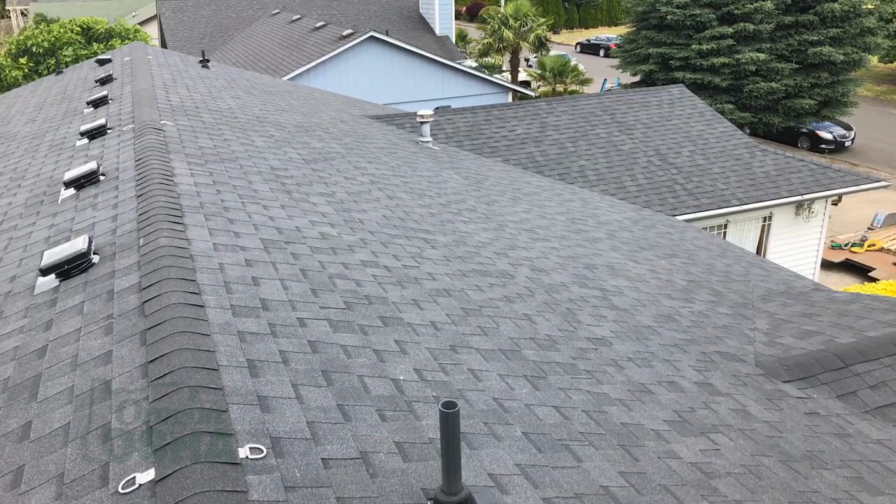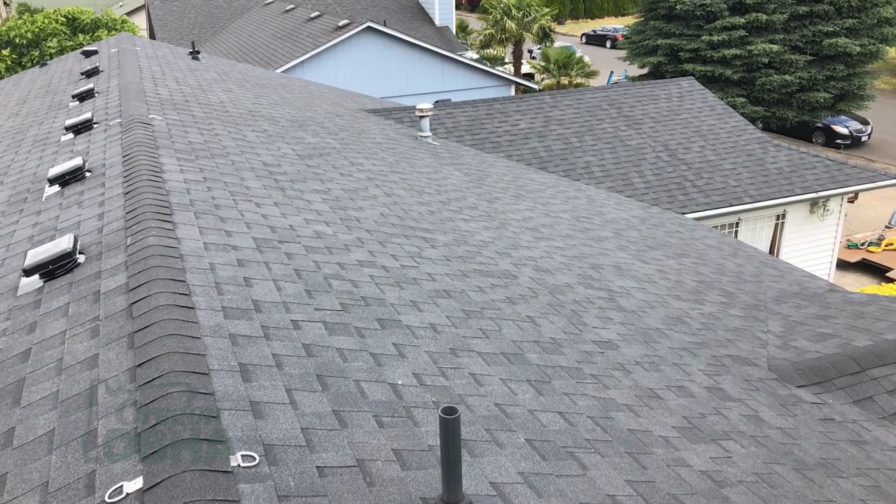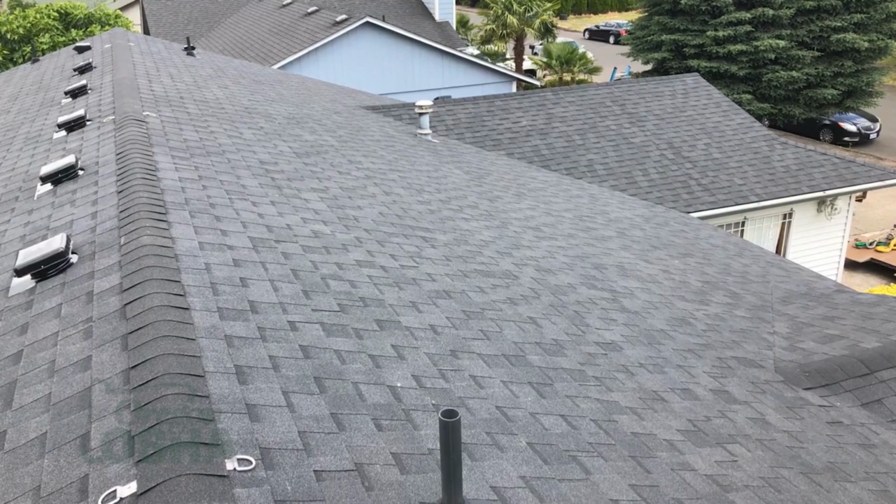So when it comes to setting up your roof for your fall protection, you have to set up the anchors in ways that prevent your swing, your pendulum swing. So typically on a residential roof, you're going to have more than one set of anchors installed because you can't put one 40 feet away and then be working over here, because if you fall, all of a sudden your rope is way too long and you're hitting the ground. So you set up multiple anchor points so that you can adjust your rope, again, to have it at the proper length for what you're working on.